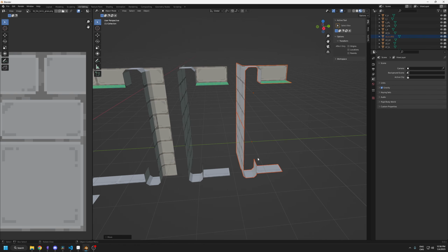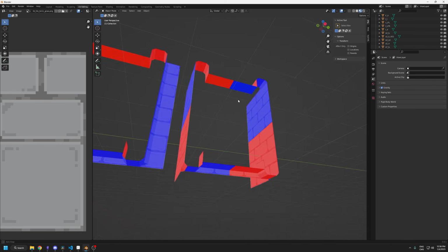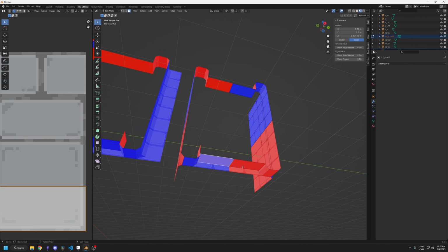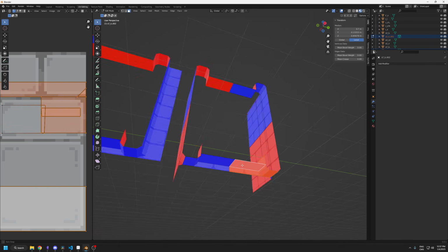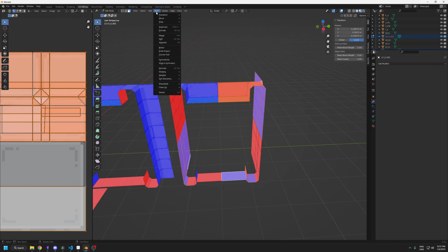I'll flip it on the y-axis -1. Then I'll need to fix the normal orientation. If I look at them, yeah. Since I only duplicated a part of it, I'll need to select manually the faces. So those ones. And then I'll select my mesh and flip the normals.